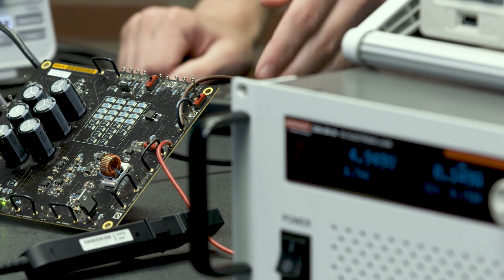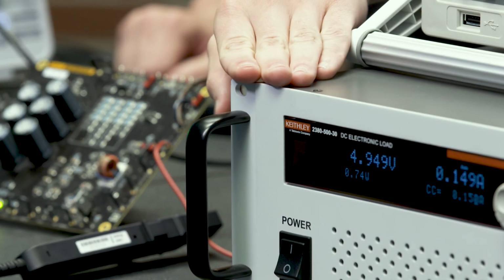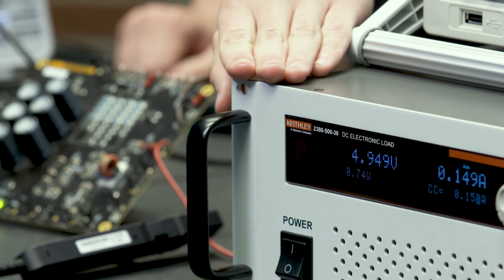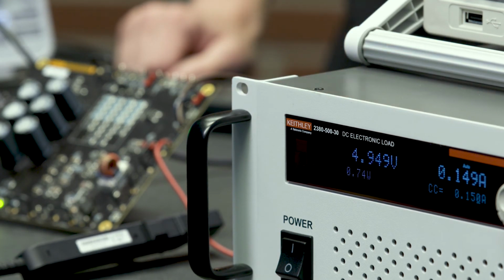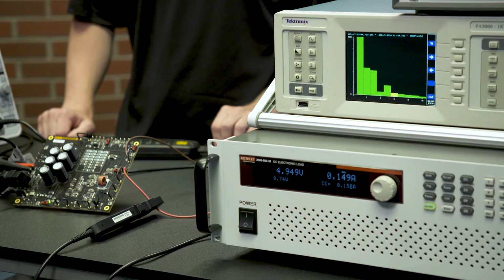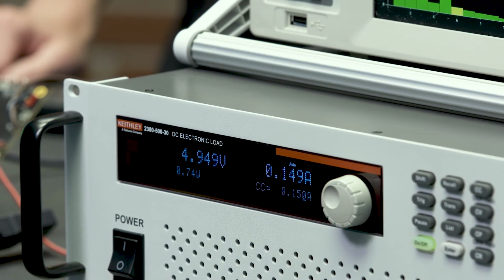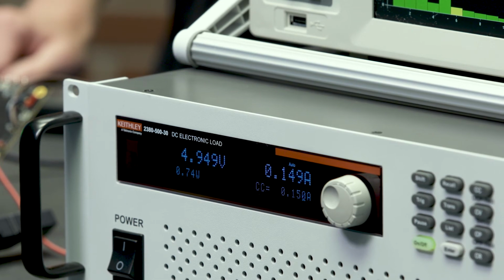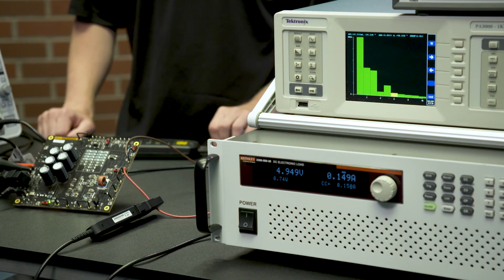Looking at our DC output, we have our 2380 electronic load, so we can control the load precisely for all real-world conditions. We have a couple of choices for output voltage and power measurements as well. It's convenient to just look at the numbers on an electronic load screen, but usually that won't afford the accuracy you need on the output DC measurements, especially where ripple information and load or line regulation is important.